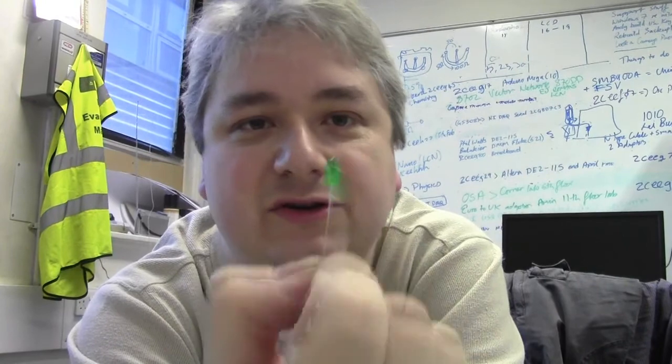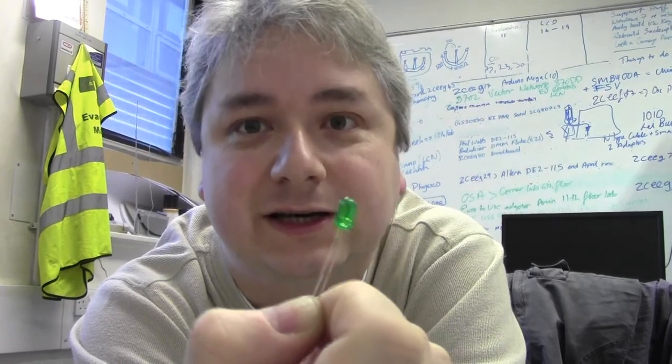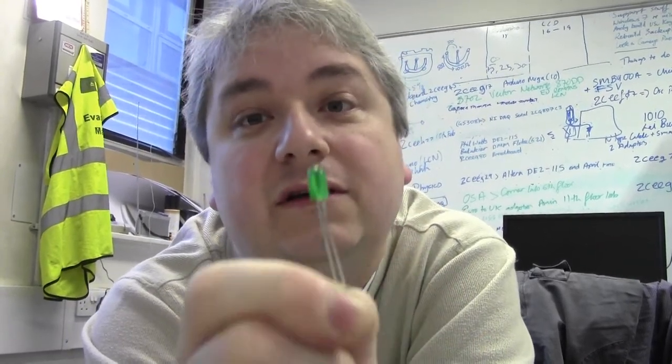Rectifier diodes, higher barrier diodes and Schottky diodes and all these other diodes all have a lot higher than these, because these will in reverse break down within a few volts. You can destroy a red LED with just 5 volts in reverse.